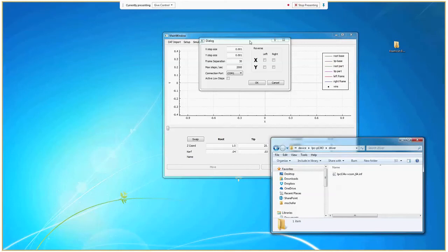So anyway, getting back to the foam cutting software, inside the setup dialog, there's a couple things we need to do to tell the software about our particular foam cutter. So the first one is the X and Y step size. The assumption is that the lead screws on the left and right are identical, but you might have used different ones for the X axis and the Y axis, so you can independently set the step size here.